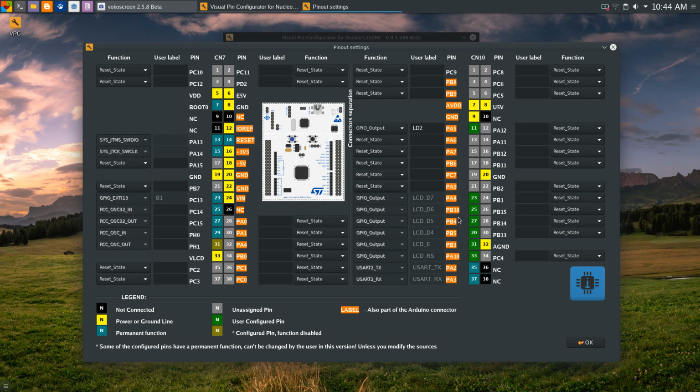And I chose these pins regarding the Arduino controller, because these are the pins that I use in the Arduino controller, and probably others do the same. It doesn't interfere with the peripherals existing on the Arduino board. This is for the default. If you use custom, then this will be reverted to reset state, and you are free to choose any other pin for the LCD peripheral.